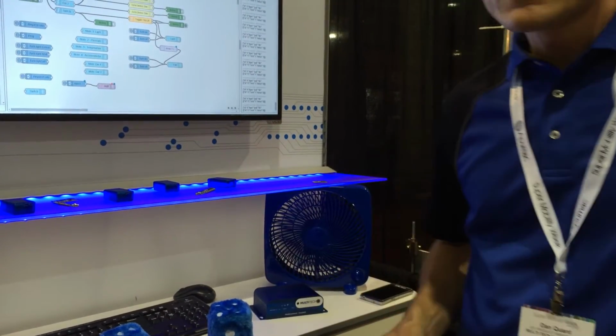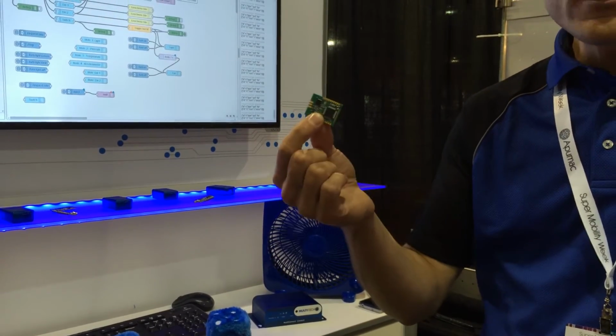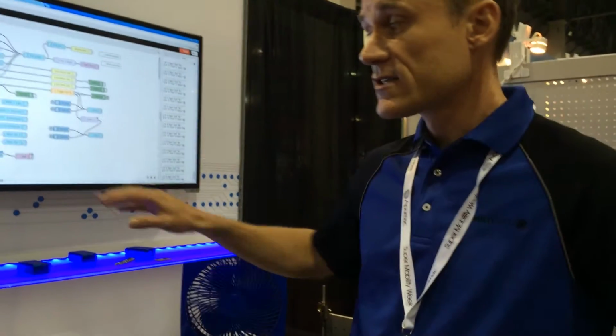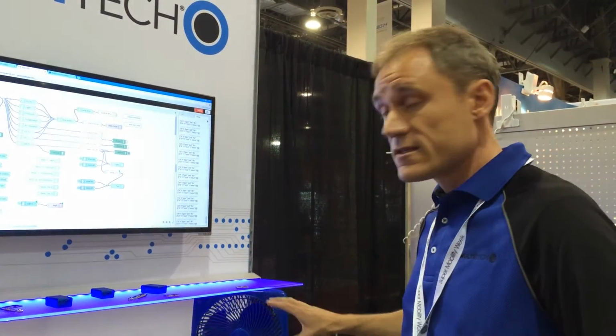The reason that we show this demo is that we show that this is a full duplex technology. We sent a message from the box to the platform. We sent a message from the platform down to the fan. It's a full duplex technology that's scalable from 22 kilobits per second all the way down to 100 bits per second, which gives it a phenomenal amount of use cases rather than just being focused on meter readings and a variety of low bit rate sensors.